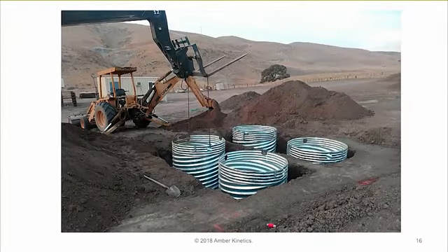Okay, so here's more nuts and bolts on how stuff is installed. This is, I believe, at our test site in Central California. This is King City, California. And these are basically corrugated metal pipes, just like the water conduits that go under roadways and so on. So designed for below-grade installation. And there's a seal on the bottom, and the flywheel unit is basically installed at the bottom of that can, and then a cover is installed on top of the can.